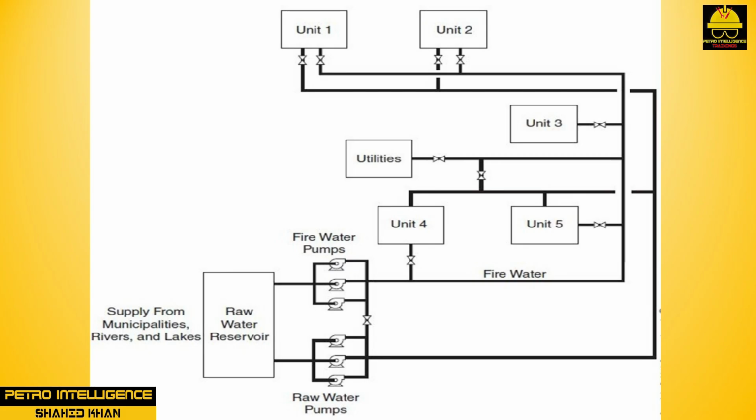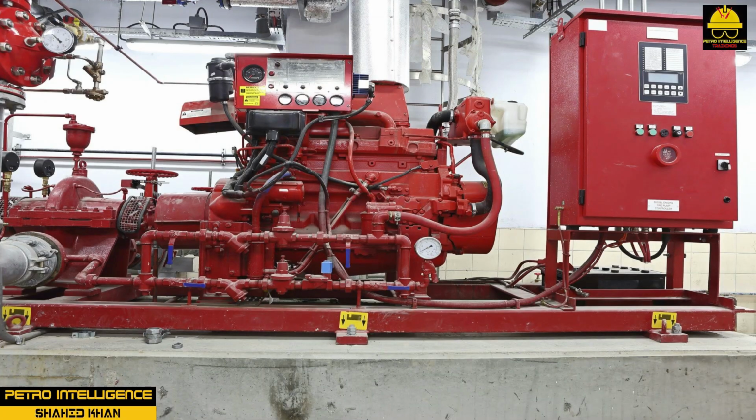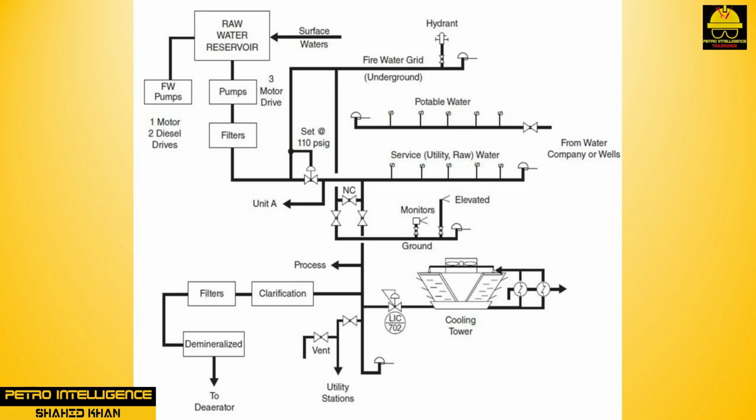Plants use raw water in utility station water hoses, process unit fire water, FW, hose reels, the cooling water supply, the supply to the fire water system, and boiler feedwater makeup. Fire water is supplied to the plant by pumps, which must be capable of continuing to run if power to the plant is lost. These pumps are typically diesel-driven to ensure operation if electric power is lost. The FW system pressure can be supported by cross-connecting from the raw water system.